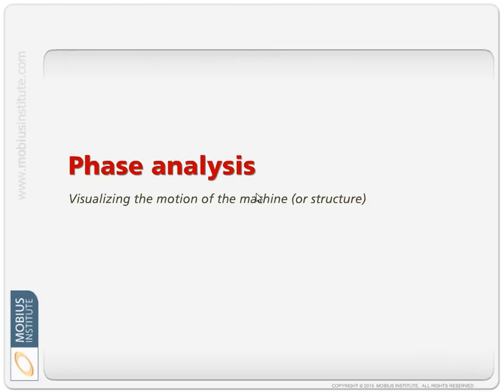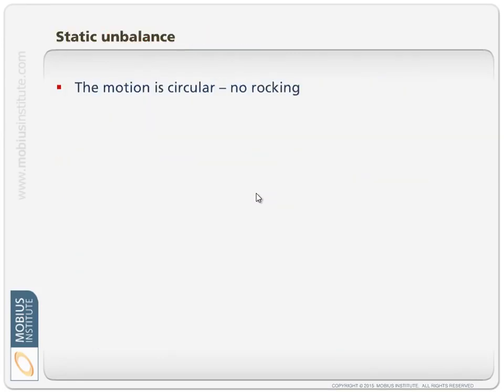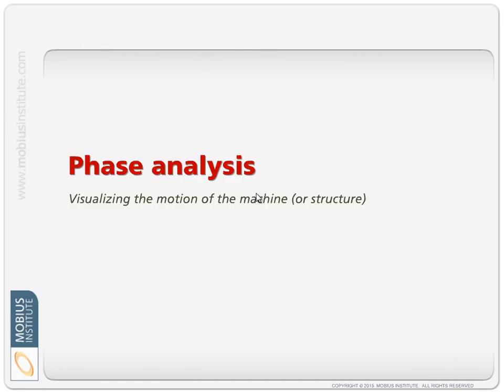There is another type of analysis we can do which also adds information, and that's called phase analysis. Now, imagine if you will, I'll come back to that. Oops, there we go. Imagine if you will that the machine is out of balance, and we can think about that shaft trying to move in a circular motion, and we can think about the vibration it would generate. But think about the machine itself. This is potentially a high-ish speed machine, whatever, just 2-pole, 4-pole, 6-pole motor.